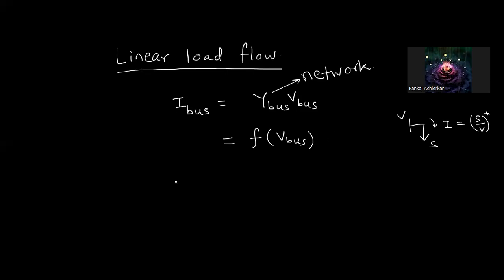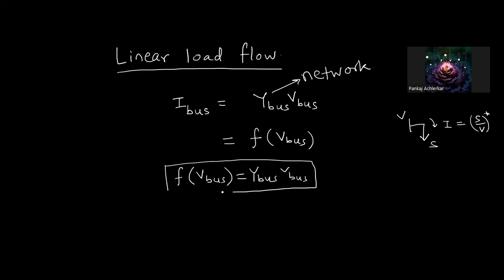So when we are solving the load flow equation, we are essentially solving this non-linear equation: F of V bus is equal to Y bus into V bus. Since there are several thousands of buses present in the system, we have a set of nonlinear equations which need to be solved simultaneously.